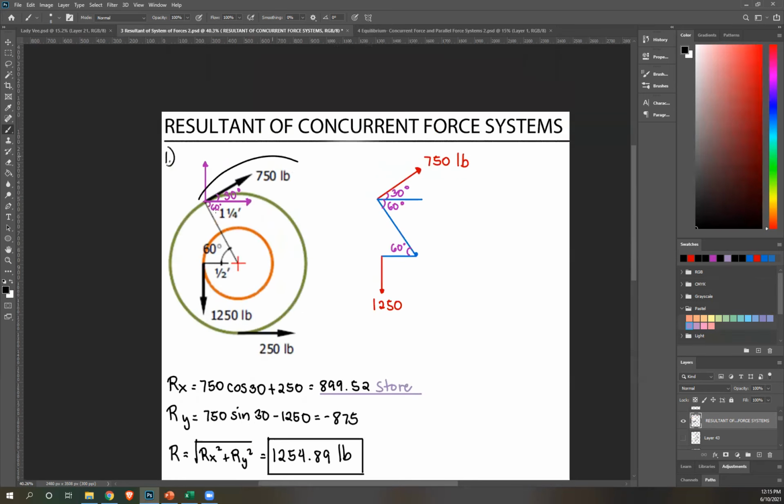Once again, let's begin with 750. Now, this is the center. It's your center C. We want to know the perpendicular distance of 750 to C. If you don't want to do that, you can take components, Varignon's theorem. However, for this specific example, as you can see, radius is given, right?